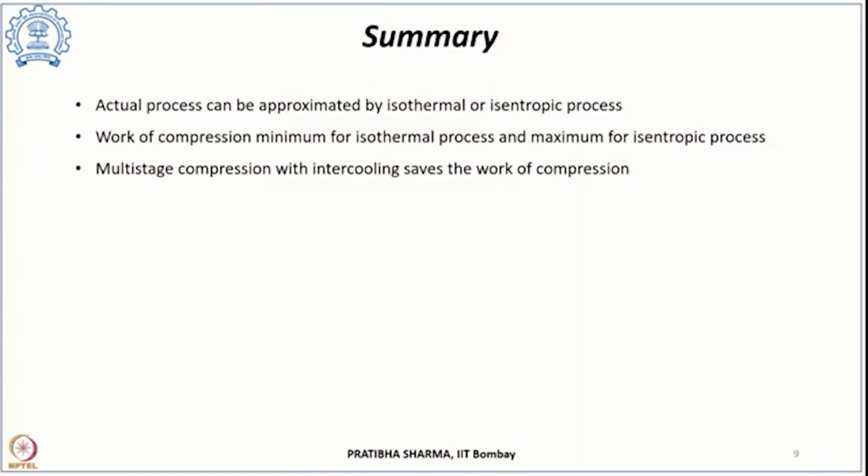To summarize this part, we have seen that it is difficult to approximate the actual process; it requires a lot of effort. As such, the actual process could be approximated by a reference thermodynamic process. It could be an isothermal process or an isentropic process, depending upon whether the compression is done with cooling or whether heat is not removed during the compression process. We know from basic thermodynamics that the work of compression required is minimum if the process is isothermal, and maximum when the process is isentropic.